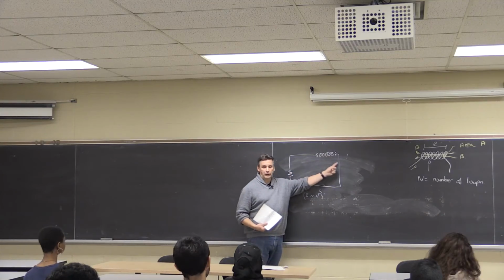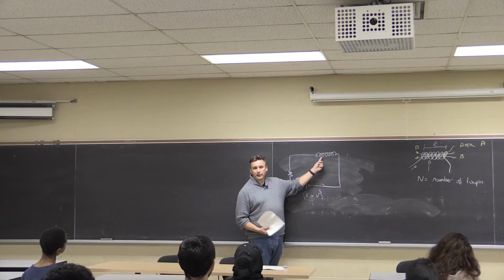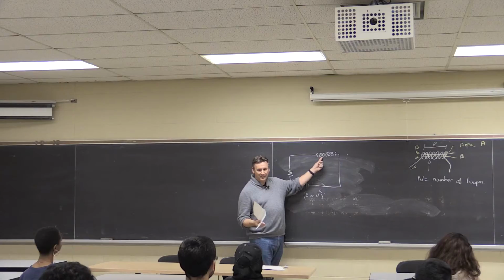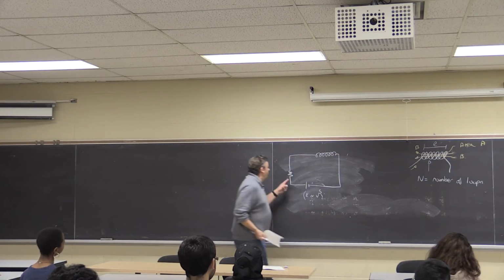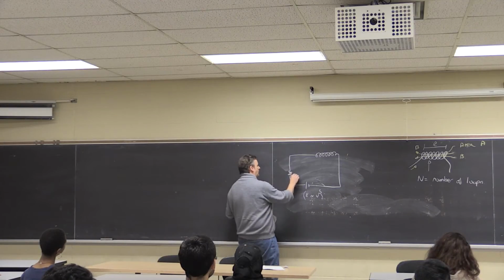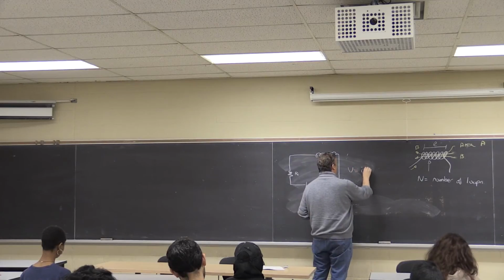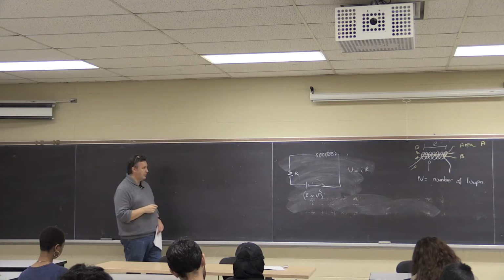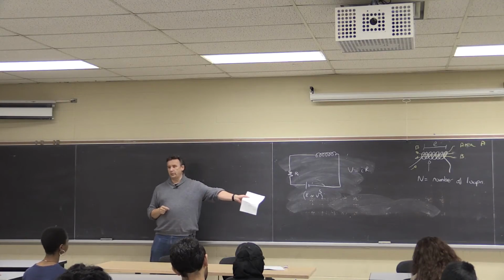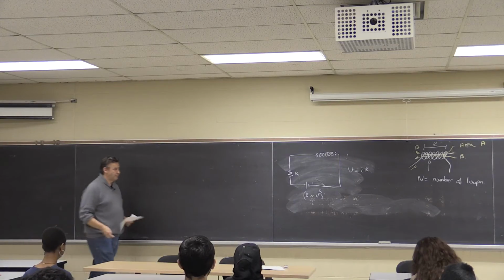There'd be no changing current, and I'd be able to say, well, the resistance of the inductor is... that's a question. Resistance of the inductor is 0. It's just a wire curled up. The resistance here, we can say it's got some resistance R. So I know V equals IR would apply. So I'm going to get a certain current flowing around this circuit. So before t equals 0, nothing happening. After a long time, constant current flowing in this.